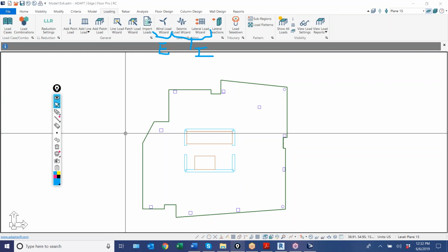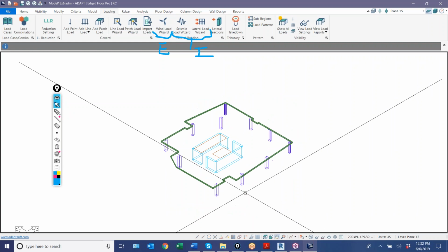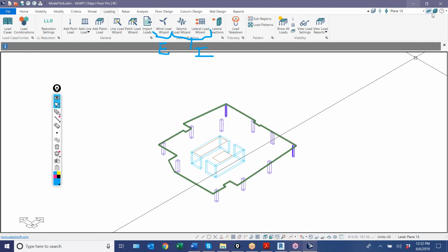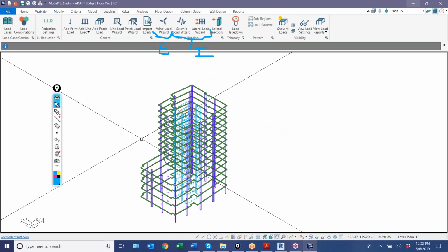Now, let's go ahead and solve this, because I want to answer a question that was brought up. In order to solve lateral load cases, we have to use finite elements in our program. If we want to only solve gravity load cases, we can use tributary, load takedown, or we can use finite elements, one or the other, or envelope the both, right?